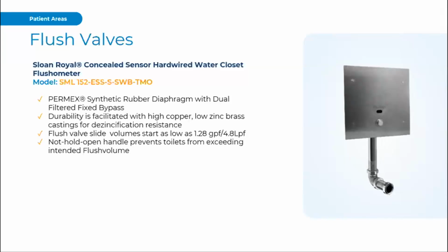So when comparing other manufacturers, the industry does try to standardize around 4.8 liters per flush. However, if we are pursuing LEED v4, there are lower flows available now. This has come up pretty regularly over the last year, where we frequently are seeing people trying to get below that 4.8 liters per flush or 1.28 gallons per flush baseline.